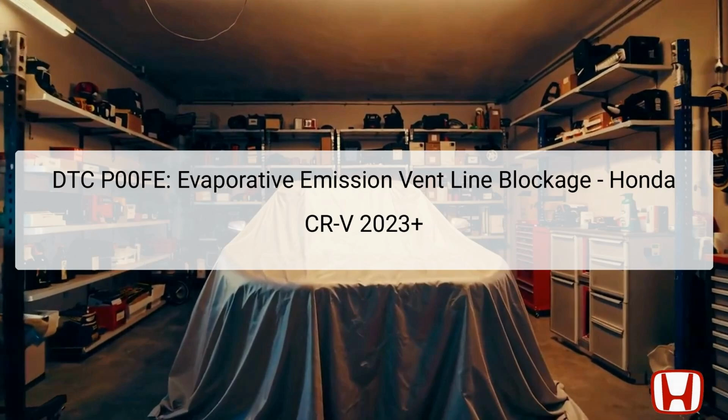The DTC P00FE indicates a blockage in the evaporative emission (EVAP) vent line, which may trigger the vehicle's powertrain control module (PCM) to record an error. The EVAP system is crucial for controlling fuel vapors, minimizing emissions, and ensuring proper fuel tank ventilation.